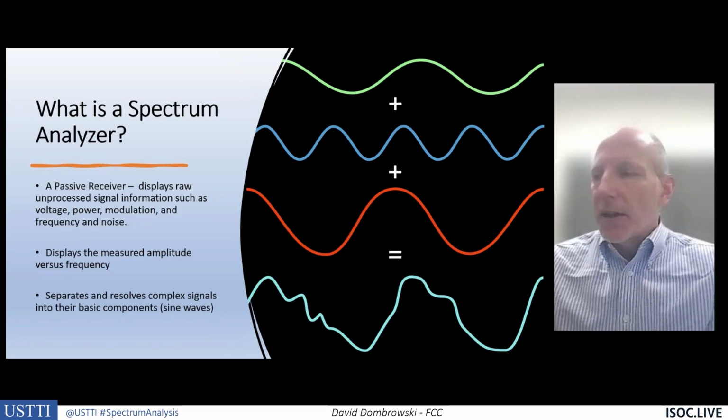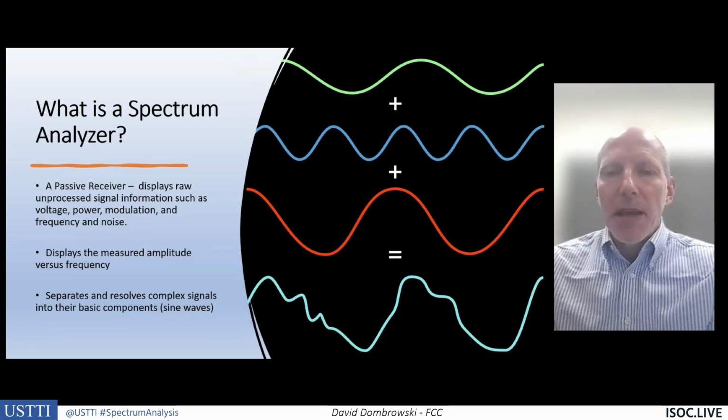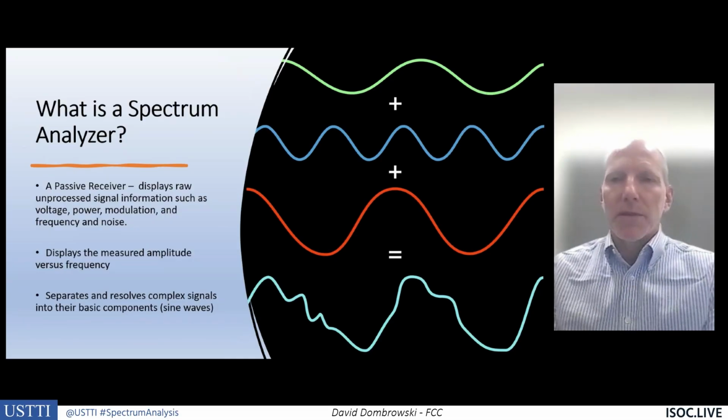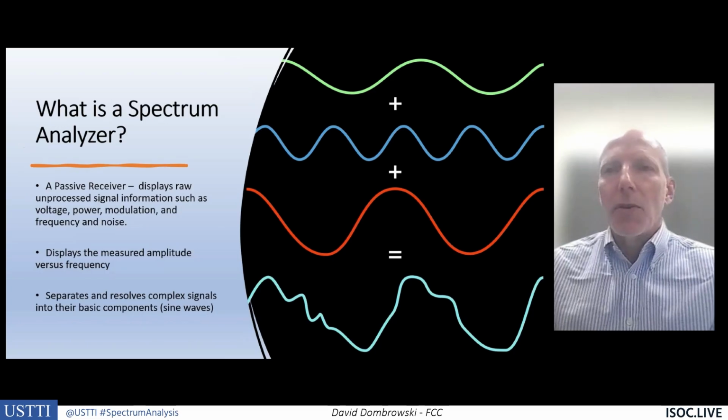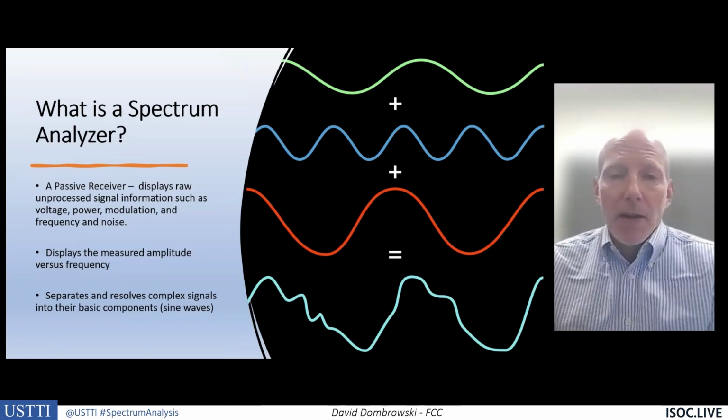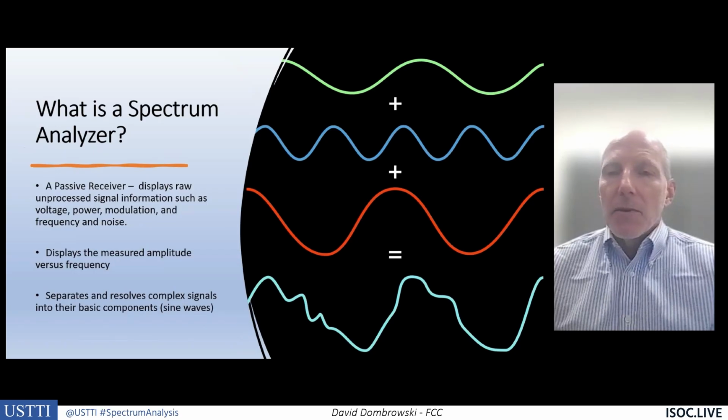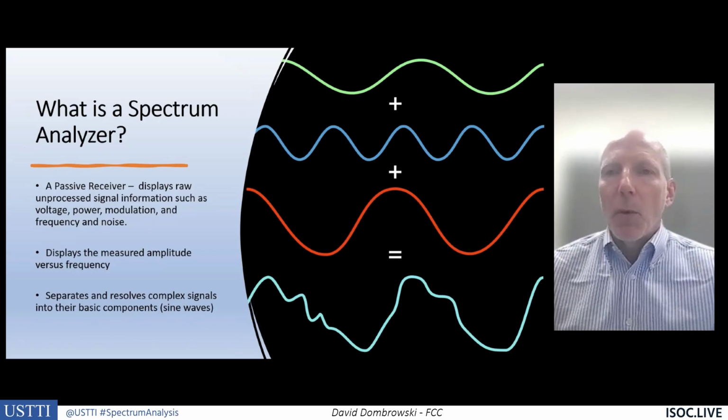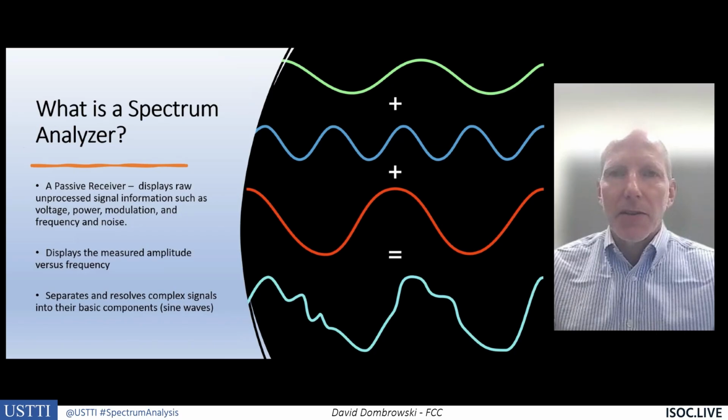A radio signal that's displayed on a spectrum analyzer is made up of many different types of sine waveforms that vary in amplitude and phase. And it's a combination of them. And what the spectrum analyzer is doing is processing that waveform so it can display it on the analyzer, and it can display the frequency versus amplitude, how strong that signal is and what frequency it's appearing on.